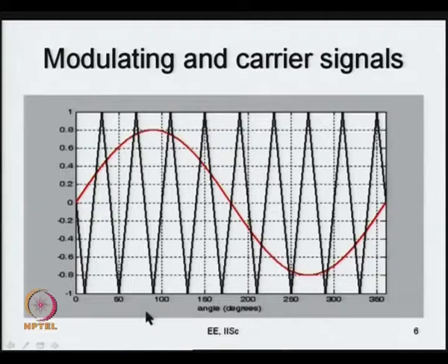In very high power levels, this could be lower. For example, where you use IGCTs or GTOs, this carrier frequency could only be a few hundred hertz. So, we have a model and, for all purposes of this study, we regard this carrier signal as a high frequency signal whose frequency is much higher than that of the modulating signal. So, in one carrier cycle you can regard the modulating signal to be almost flat. So, any change that you have can be ignored now.